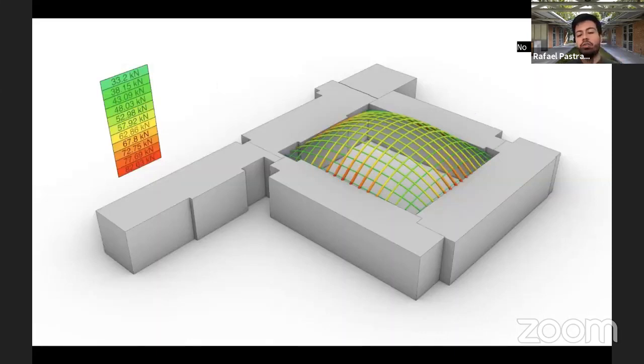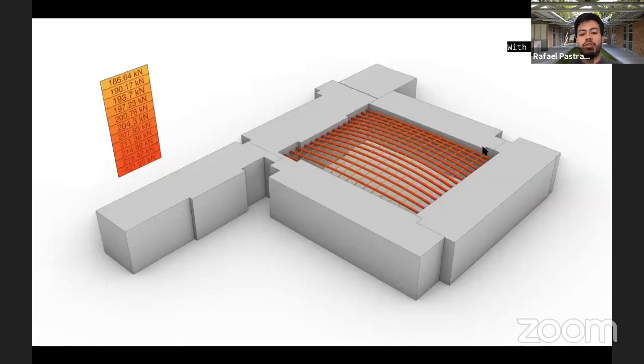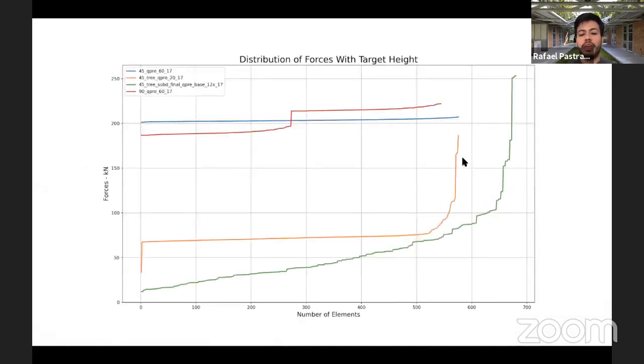So this one is actually 10 meters higher than what we were supposed to derive. So when we apply the constraint, you see that the forces dramatically increase, actually threefold, to find a shallower version of the shell. So when we apply the constraint to all 4 examples, we see that the green option, the selected, subdivided one, was actually a reasonable solution.